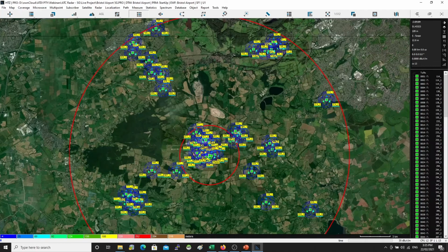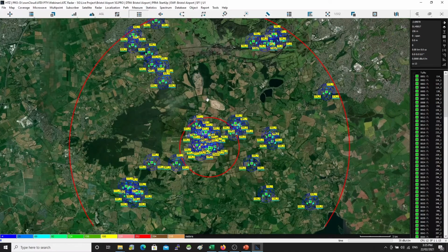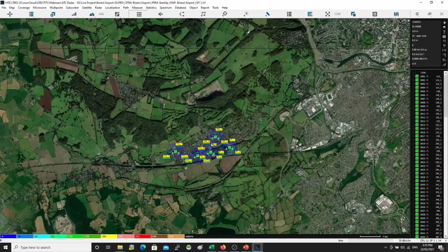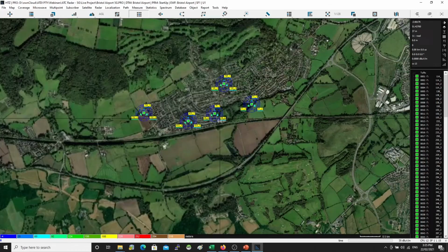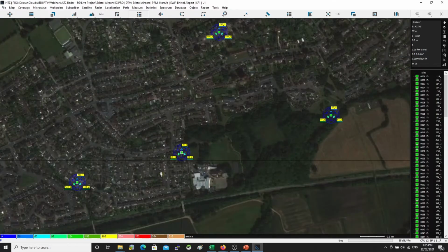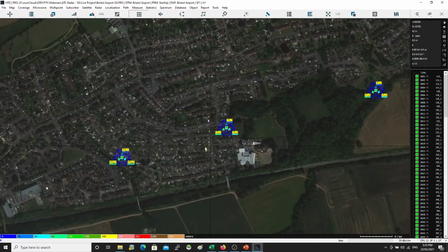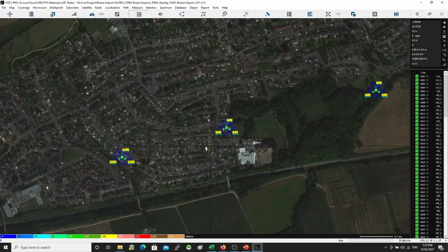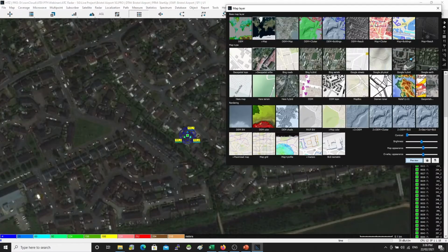Now, one thing you need to know, with the propagation model ITU 450, which is used for the terrestrial coordination process, you need to make sure that the antenna heights of these sites are actually exceeding the clutter height. For example, I'm usually worried if the site is sinking under the building. That happens if the building height is above what you expect, or if the antenna height is below what is expected. Sometimes the source is not very clean, so you need to be careful.